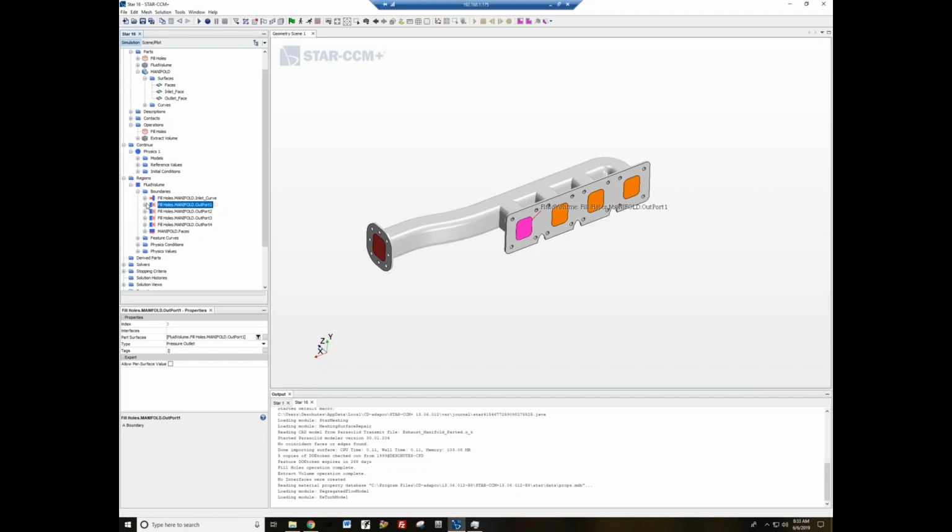That's based off of the reference pressure. So the next thing that we would have to do is to mesh this region. We've now got our boundary conditions applied. It is important to apply the boundary conditions before meshing because it helps guide the meshing structure. And we will see that in a little bit.